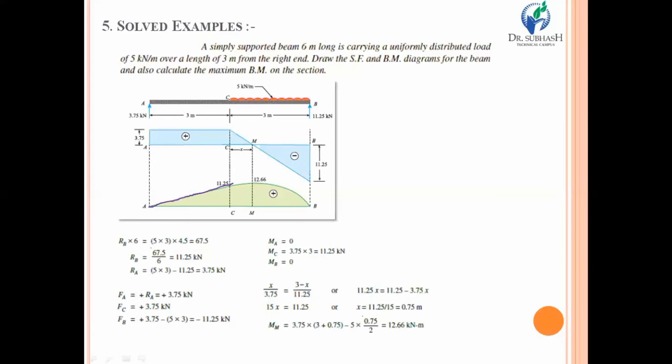Similarly, while you are drawing the bending moment diagram, if there are two sections in which the UDL is acting, then both of the sections should be joined with a hyperbola, or we can say a simple curvature line. By joining that, you have the bending moment diagram. So this is the first answer: we have calculated and drawn the shear force and bending moment diagram.